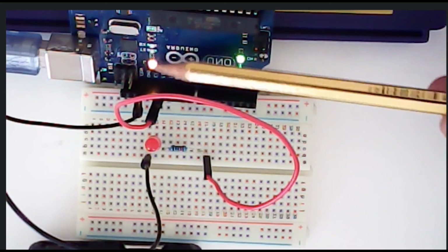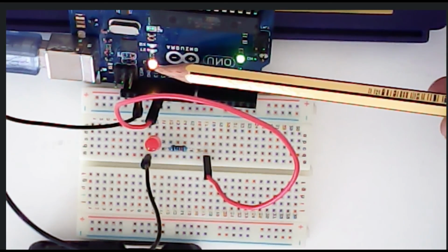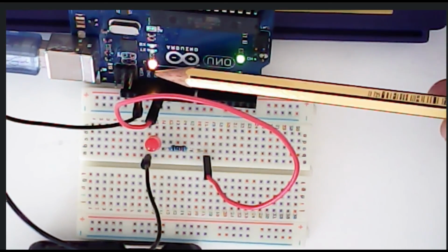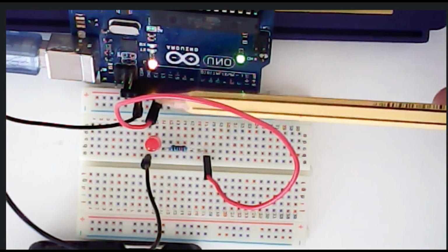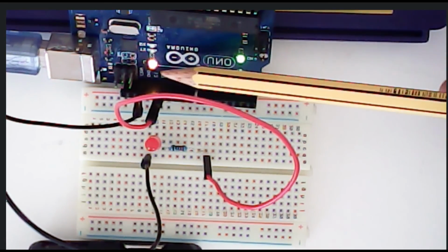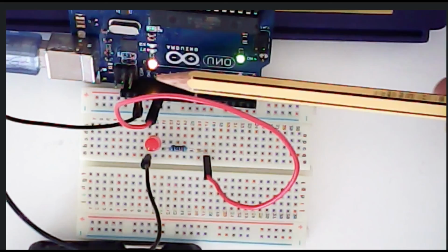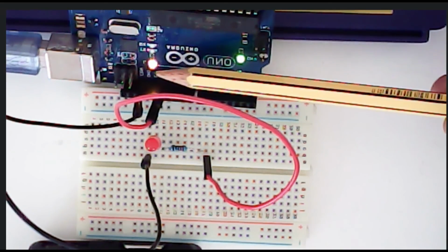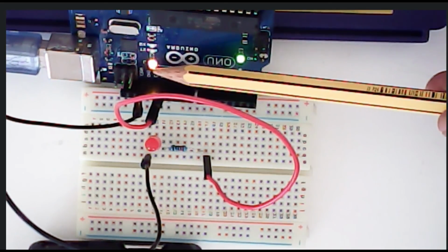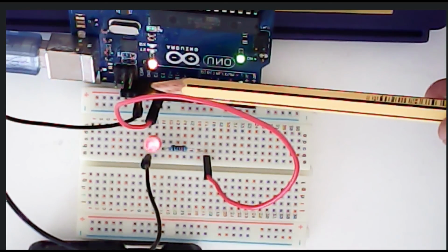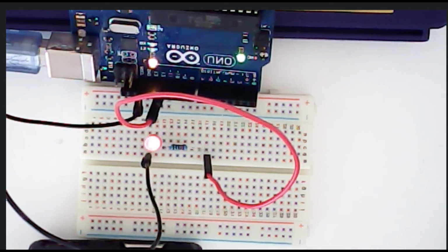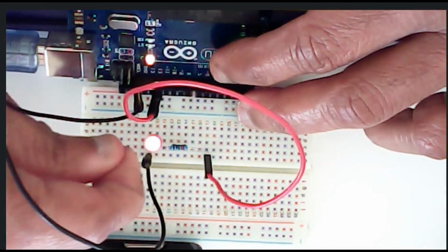But how do I turn this pin number 13 LED low? There are two ways to do that. One is you can modify your Arduino sketch to turn this off. The second way is you can connect a 10K resistor to the ground. So if I connect a 10K resistor to the ground, let me just connect a 10 kilo ohm resistor, pin number 13